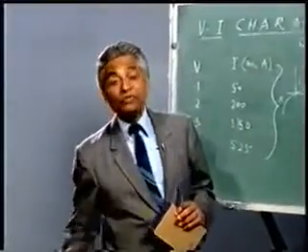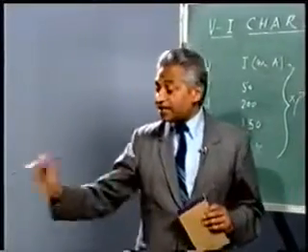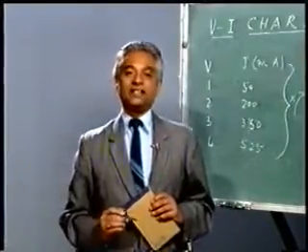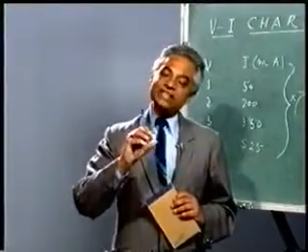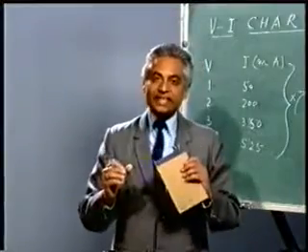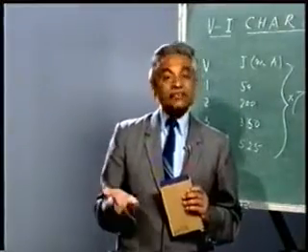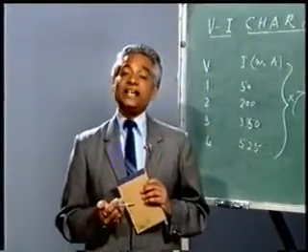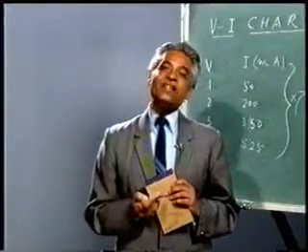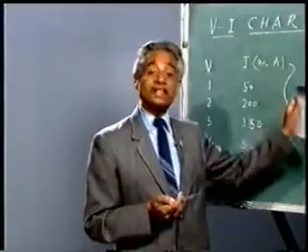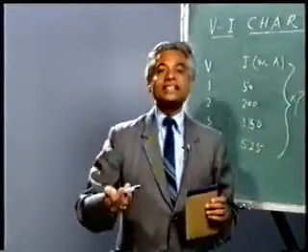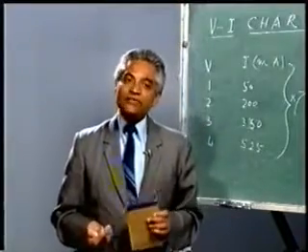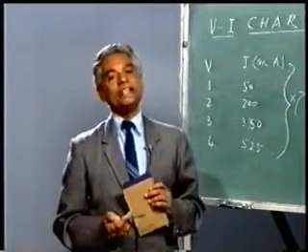The second point we have verified is that the conduction of the device is regulated with the help of the gate current. We can trigger the device by changing the gate current, and once we change the gate current, the device will conduct at different sets of voltage applied. The third thing we have verified is that the VI characteristic of the device can be plotted at different sets, but the shapes remain the same. So, that on the whole verifies the VI characteristic of an SCR.